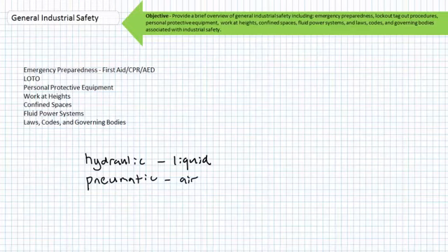An injection injury is when high pressure forces oil into your body. Such an injury may require amputation of the affected limb or involve surgery. Immediately shut down a hydraulic system if you discover a pinhole leak and never attempt to stop the leak with your hand or any other part of your anatomy you wish to keep.